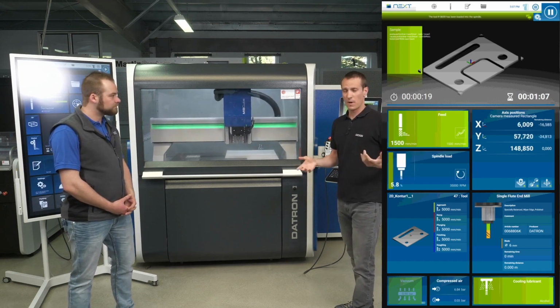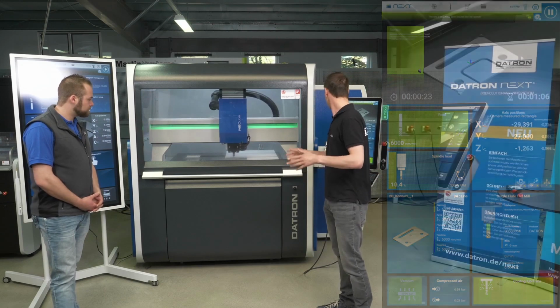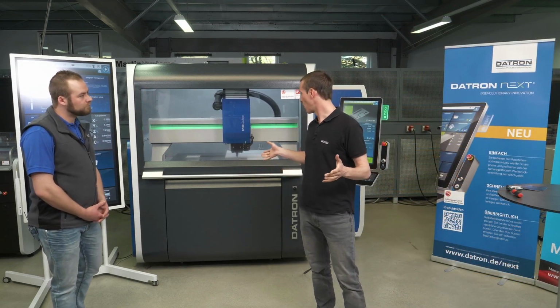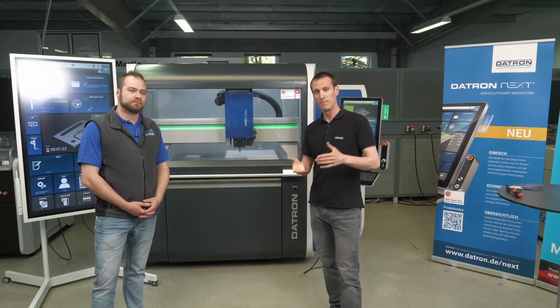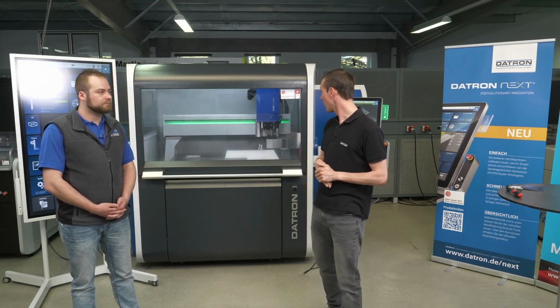So there's nothing special on this part to see now. It runs for a minute or so. So pretty straightforward. We're cutting something out on the vacuum table. We're going 3/10 deeper than the actual stock size. And then just taking the part, very clean edges, right out of the machine.